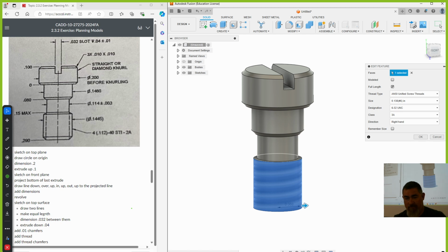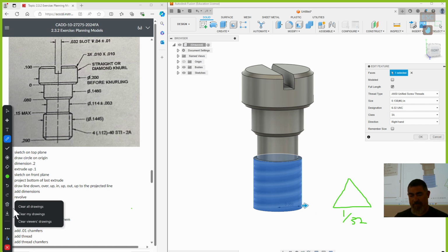line, right? If I look at the thread, it's a triangle. This is the inside edge. This is your 1/32 now. That depth there, that's the depth of the thread. Easy way, we just estimate it. We just use the same as the pitch for the chamfer. It's close enough. The chamfer doesn't have to be exact, so we'll just do a chamfer of a 32nd also.